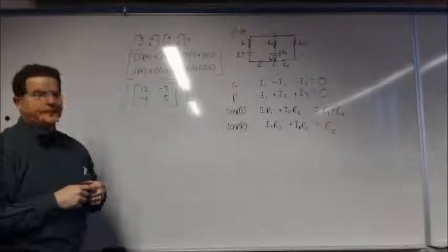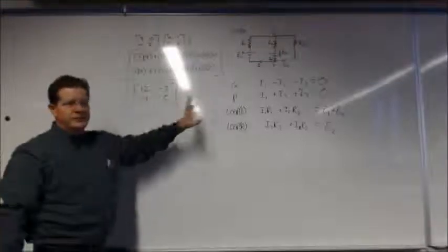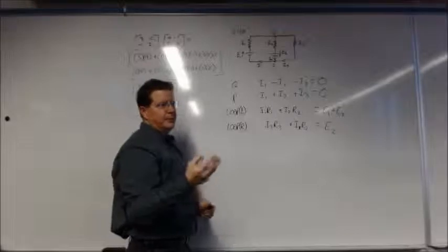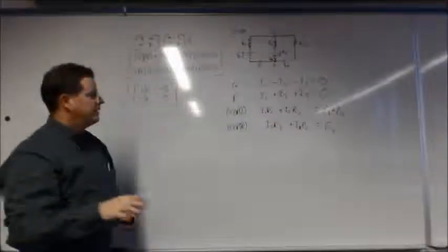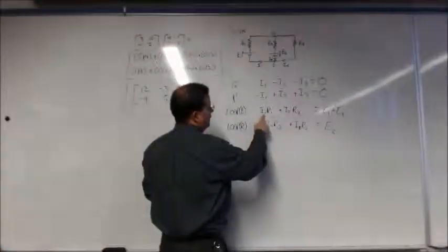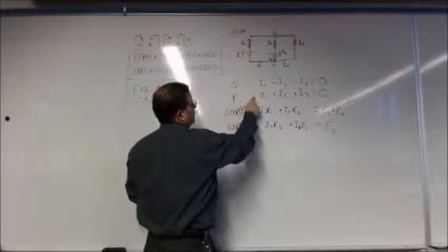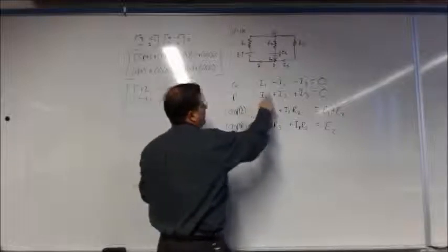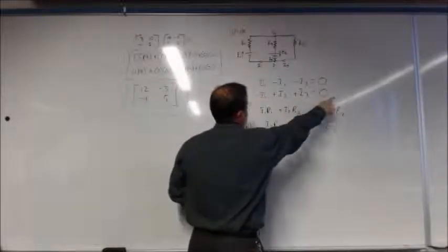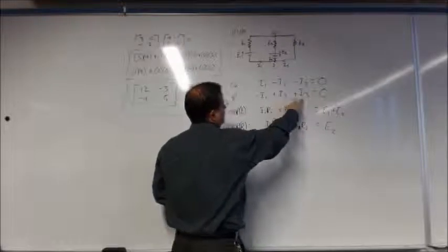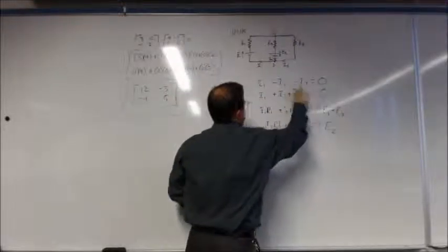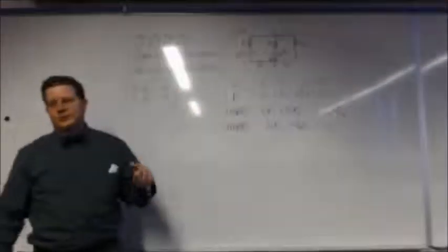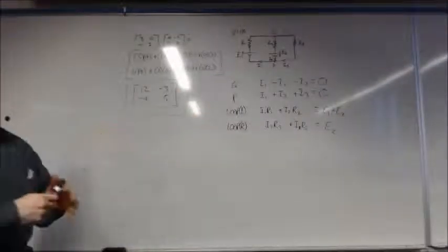Questions? All you're doing is just setting up the equation. Now, again, remember we talked about being overdetermined. We got 4 equations and 3 unknowns, because our 3 unknowns are the I's. But if you look at this, if I move I1 to the other side, it's I2 plus I3. So these essentially equal the same thing, so we could take one of them away if we were actually solving.